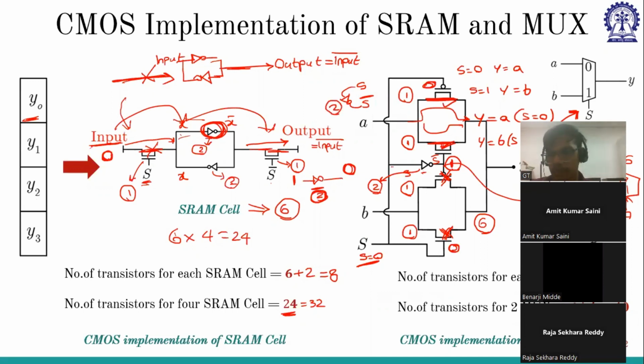I am saying this mux and this mux both need B and B bar, right? You don't have to generate B bar for this mux separately and for this mux separately. You can use the B bar that is being generated for this mux for this mux. Understood? I'm saying you don't need 2 inverters. The same signal you can use for this mux. So this won't need the inverter, and that's why here we'll need only 4, and here you will be needing another 6. You are saying that the select line for these 2 muxes is the same, right? So we don't need a separate implementation. We can share the same signal for both the muxes.